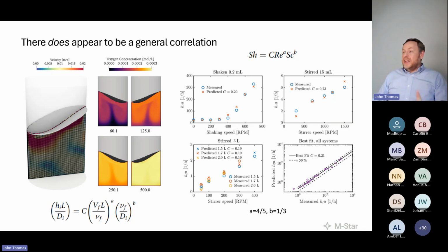And it's very compelling to me that we can get all this data from the simulation, because all we need is the specific surface area, that's the area of the interface over the volume of the fluid, and the mean velocity of the interface, to derive an interface Reynolds number. To be able to convolve those into one correlation to rule them all is pretty compelling to me.